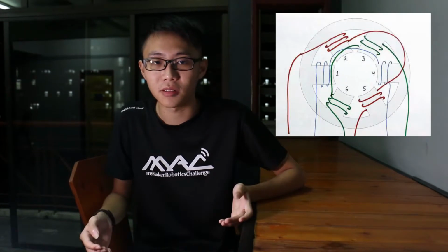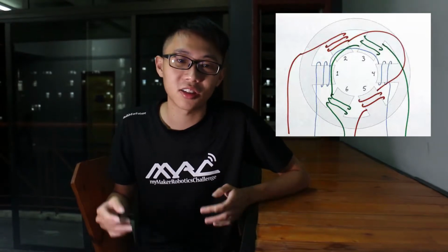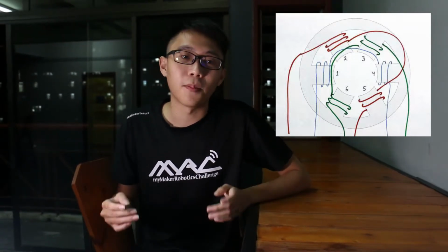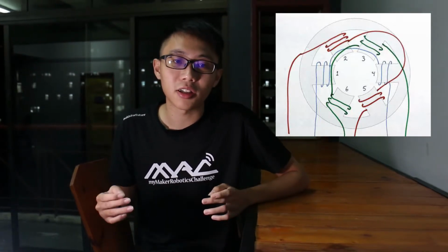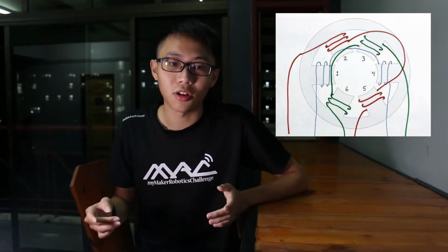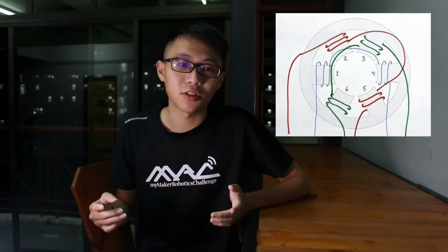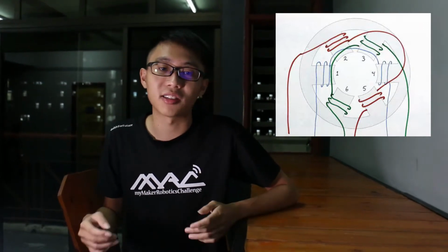In a typical three-phase AC induction motor, we create a spinning magnetic field by applying electrical current to different windings at different times. According to the diagram, imagine a current passes through the blue windings so that pole 1 is north and pole 4 is south. Next, we pass current through the red winding so that 2 is north and 5 is south. Then through green, making 3 north and 6 south. And then again through blue, but in the opposite direction as before, so that 4 is north and 1 is south. This will produce a rotating magnetic field.